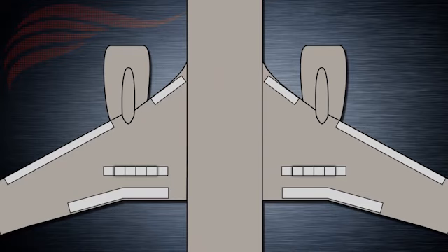Flight spoilers are used to achieve significantly higher rolling moments around the airplane's longitudinal axis. These are a series of panels on the upper surface of each wing that rise when extended, thus creating an enormous amount of drag. Flight spoilers are only meant to be an aid to roll control, not the primary roll control method. There are 12 spoilers on each wing, numbered 1 to 12 from left to right. The most outboard and the most inboard spoilers on each wing are ground spoilers. Only the 4 flight spoilers on each wing provide roll control.